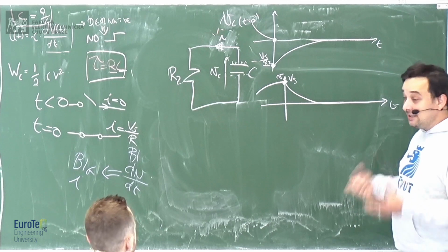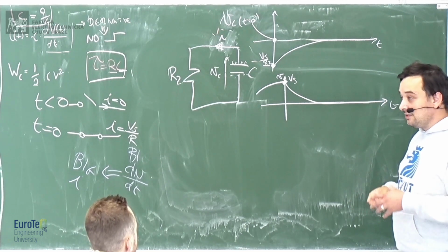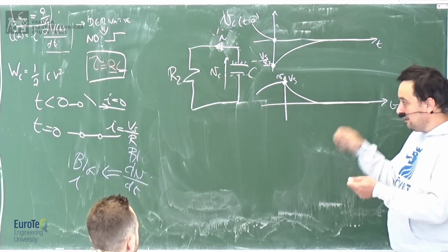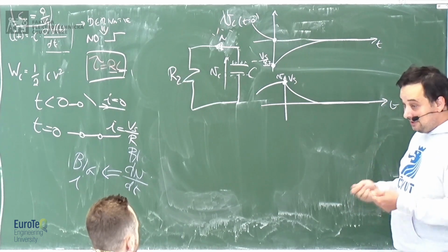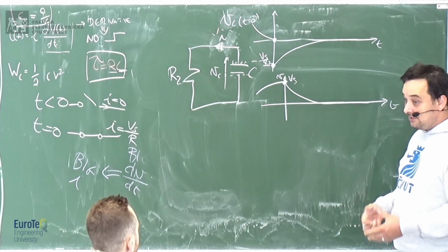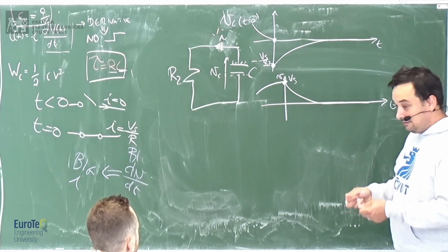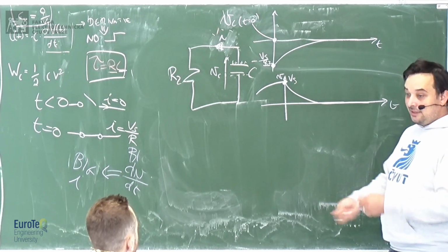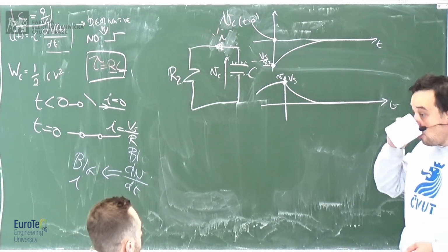So when you have some very large capacitor in your circuit, it's always a good thing before you start probing around to put some resistor there and discharge it. If you measure that there is some voltage, and it's a large capacitor, just discharge it first and then start probing around. That's why there are also bleed resistors on the power capacitors.